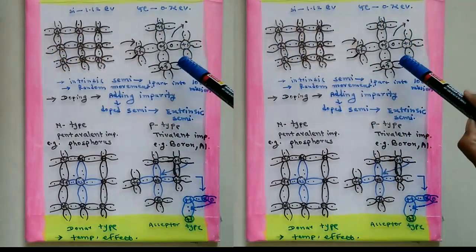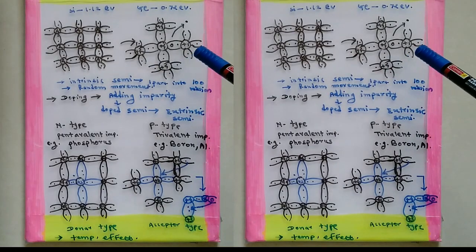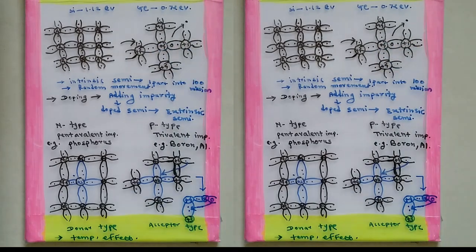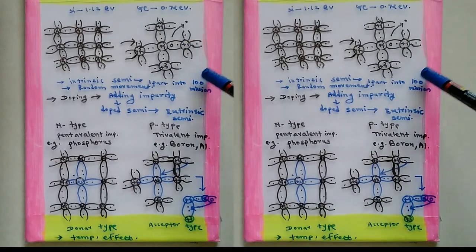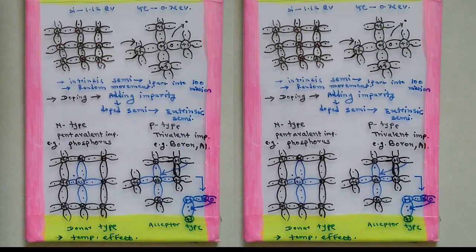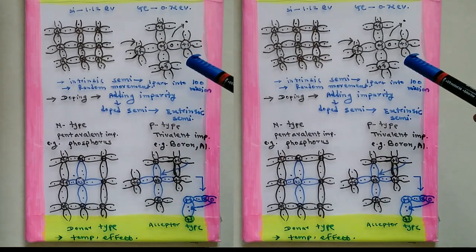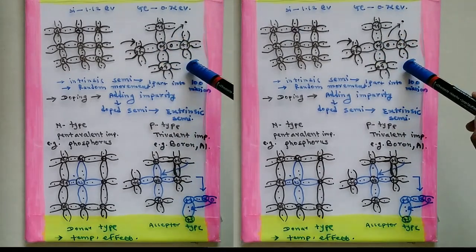So this type of semiconductor is called an intrinsic semiconductor, which is in its purest form. But remember, its purity is obtained by a separate manufacturing process, where they consider only one part impurity in 100 million parts of semiconductor. Then this material is considered an intrinsic semiconductor. And here the electron-hole pair generation and the motion of electrons and holes is random at room temperature.